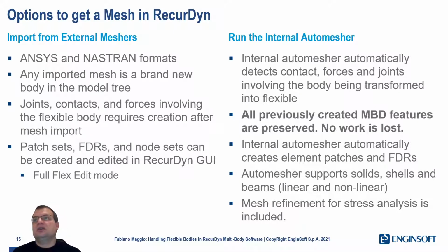You create a mesh outside, you set a coordinate for a master node that is not correct. When you import the body, you discover that the master node is not in the right position. So then you have to go outside again, correct the mesh, and re-import the mesh again. If you mesh internally, all of these mistakes will never occur.